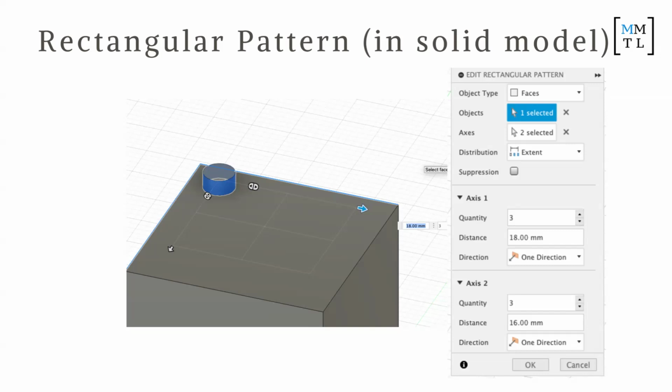Alright, if you're done with that, try thinking about how you make a circular pattern instead. You just use the same thing, but I'll say you can do a circular pattern instead. But make sure you don't create a new body next time with extrude, then it's hard to go back.